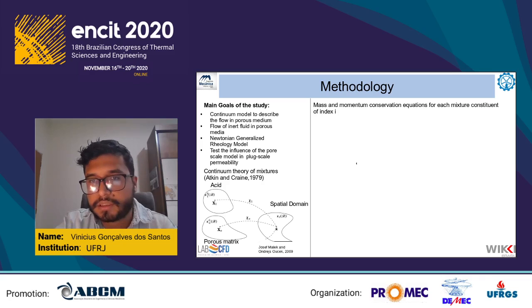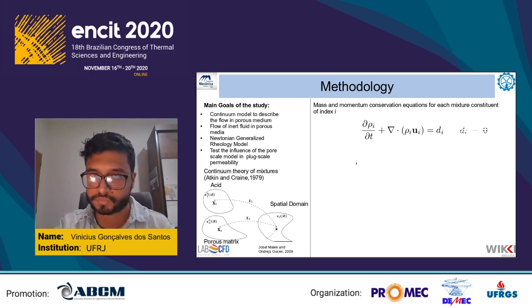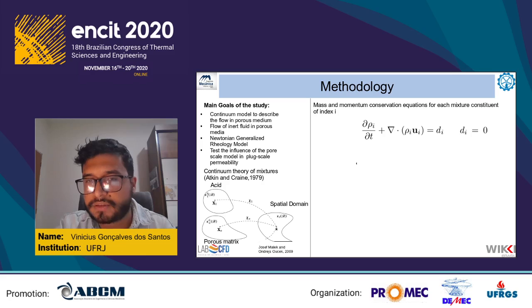Each component of the mixture has its own equations of mass conservation and momentum conservation. Here we have the mass conservation. And since we don't have a reaction, the right side term of this equation vanishes.